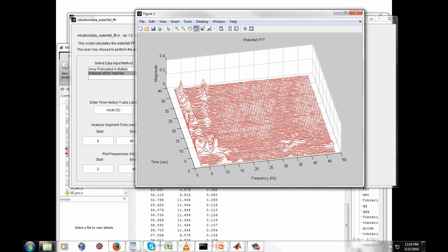There's actually another series of peaks at about 5 hertz, and what's going on there? You'll see that the frequency isn't really changing as much as we can detect. So what's actually happening? This is a spin-stabilized vehicle. It's actually spinning around, and if you go to the YouTube video, you can see that spin motion. And 5 hertz is actually the 2 times integer harmonic. The fundamental spin rate frequency is actually about 2.5 hertz.